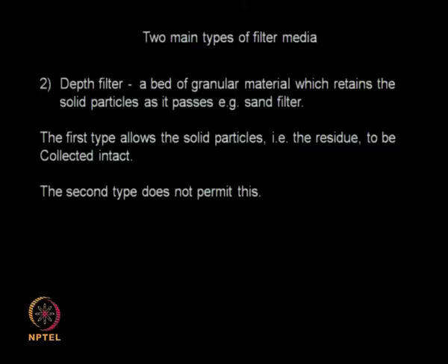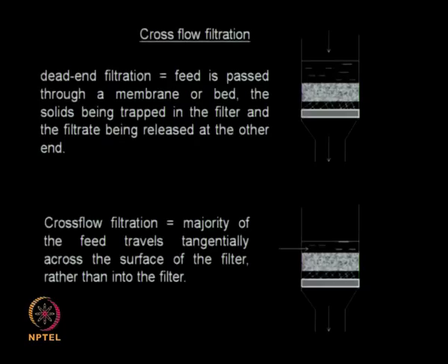Whereas if the amount of solids present in your slurry is very large, a surface filter or belt filter is the best approach. There is one way of doing filtration apart from the normal way which you all know. This is called dead end filtration.